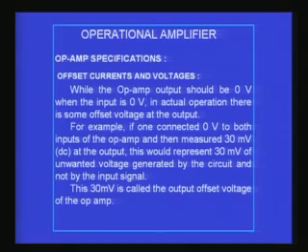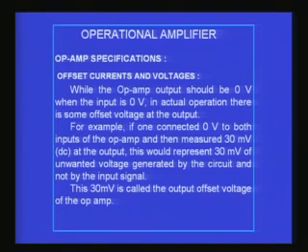So, that means what? Without giving any input, you seem to be getting an output, even though small. So, this output that you get when you make the input voltage 0 is what is called the output offset voltage of the amplifier. This, of course, as I already mentioned to you, will depend upon the applied power supply voltage and various other conditions, environmental conditions.